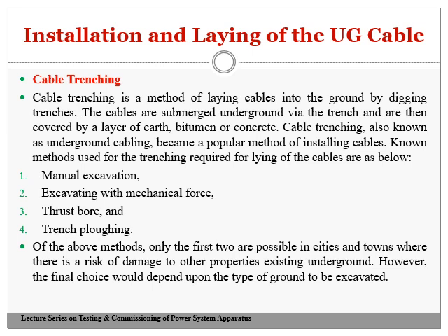Only about 2 methods are mainly used, because in the cities it becomes very difficult to use the other methods, like thrust bore or trench plowing. At the time, it may cause damage to the underground system of the planned city. That's why the first 2 methods are used. However, the final choice would depend upon the type of ground to be excavated. If it's hard, and manpower is not possible, then I need to go for a thrust bore or trench plowing.